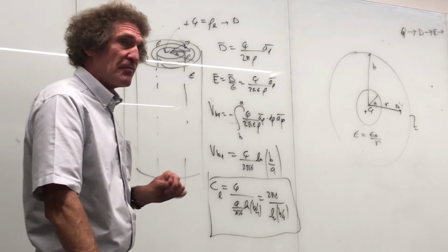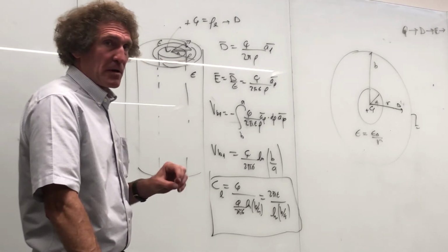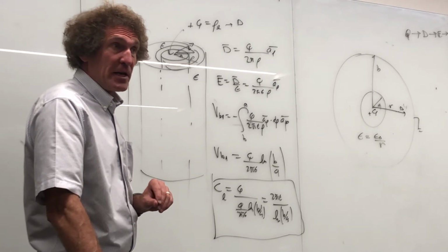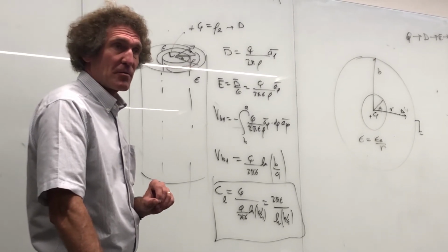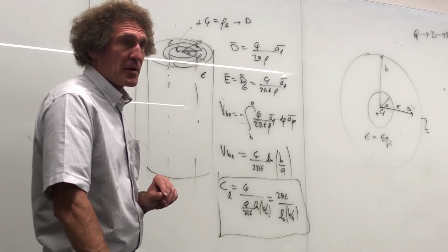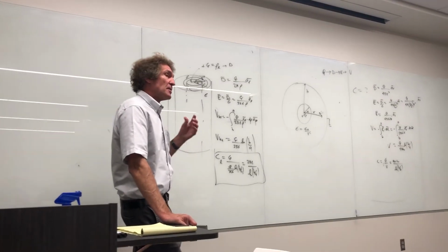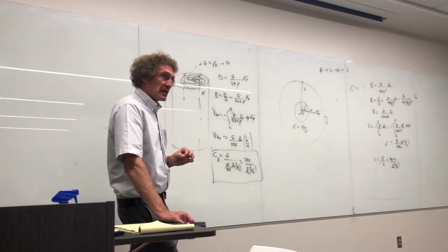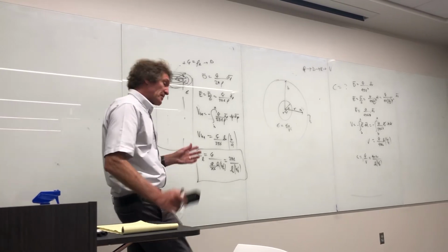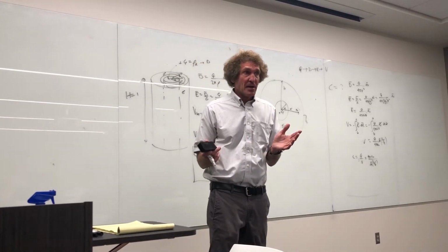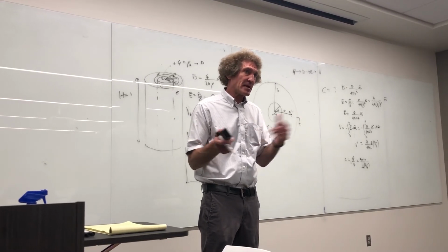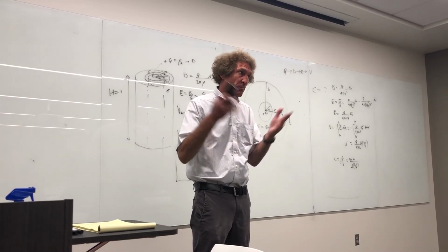I used the word self-healing. Can you think of any capacitor that is self-healing? It means the dielectric will heal once it's broken down. There's one particular kind: any dielectric that's made of oil. There are transformers that use oil as an insulation, and there are capacitors that are oil filled. The reason is that if they ever break down, they're healed, unless they blow up. I mean, if there's a continual breakdown, a continual arc, it'll heat up and blow up.